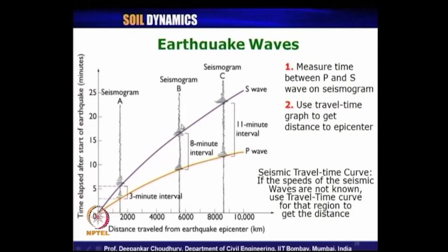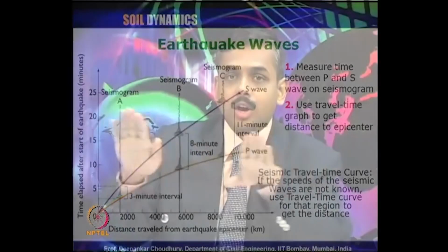Now, we try to match these 3 locations in the graph sheet in such a way that their individual distances between the stations and the time intervals follow a continuous pattern. That can be easily done by changing the positions of those seismograms and their distances.